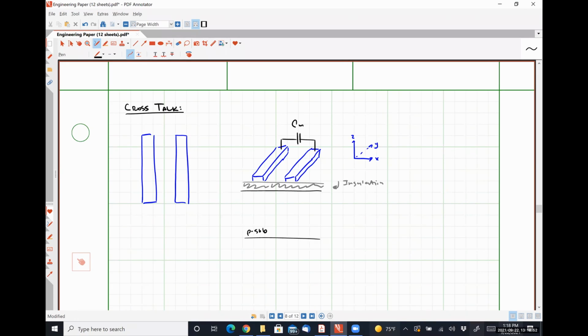So a voltage propagating on one of the conductors couples current onto the opposite conductor, right? Because if there's charge moving here and this guy is close enough, it's going to attract the charge in the other plate. And so we have capacitive coupling.